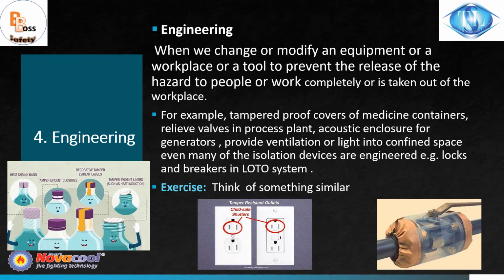Also guards: you have an electric fan in the house or in the workplace, and the guard that covers the blades is a design control, an engineering control. Now we come to the point of suitability. This fan, I cannot use it, for example, in a kindergarten because the children's fingers can pass through. So suitability of the solution depends on where I'm using it.